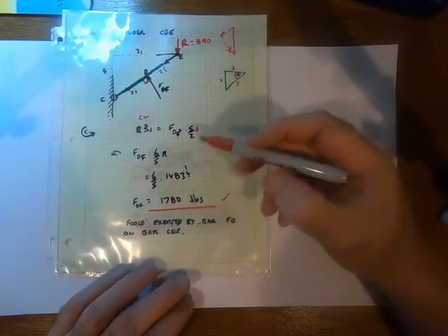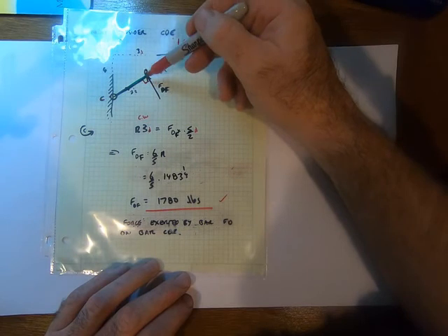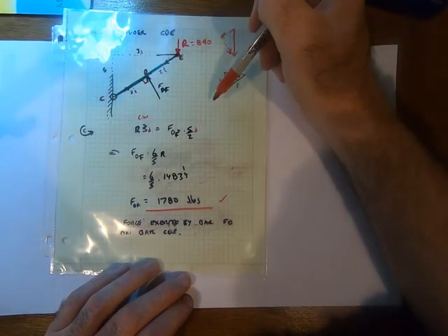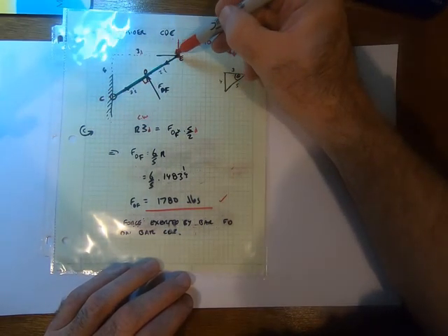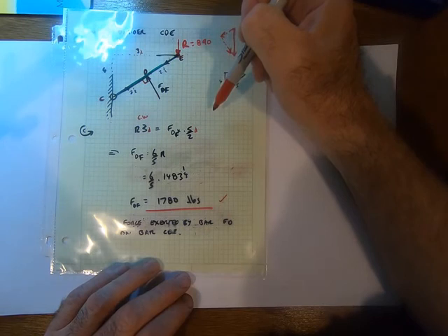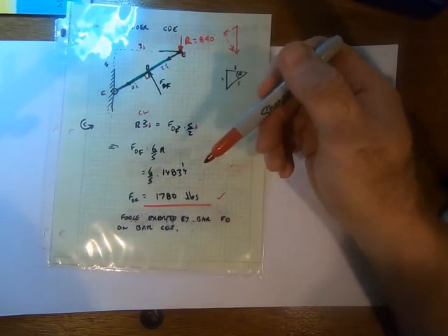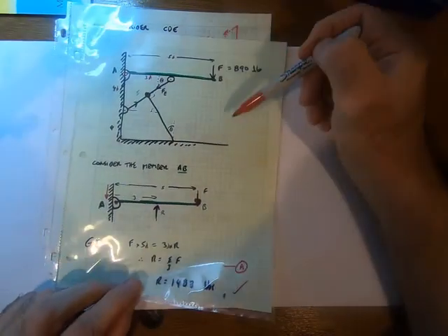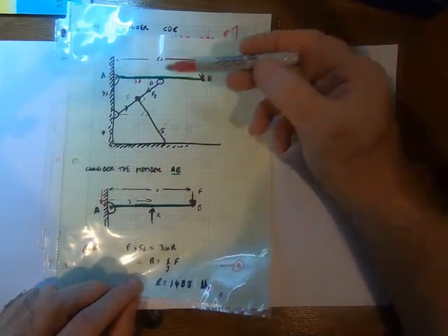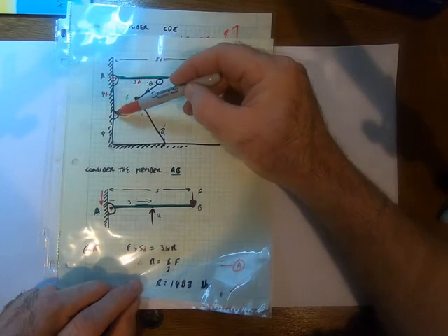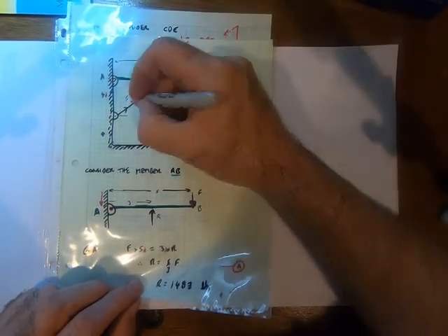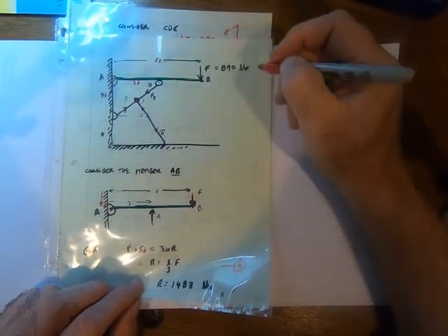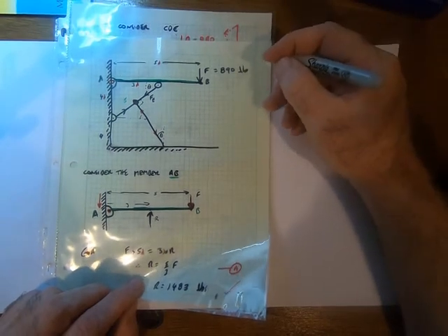And that's the compressive force that's in that bar that's holding that cantilevered beam in place. So again, much simpler problem than the last one. It doesn't look like it's going to be simpler to begin with, but all we did is take moments about this point and then this point, and we've solved for that compressive force there. So again, no resolving vertically or horizontally required there.